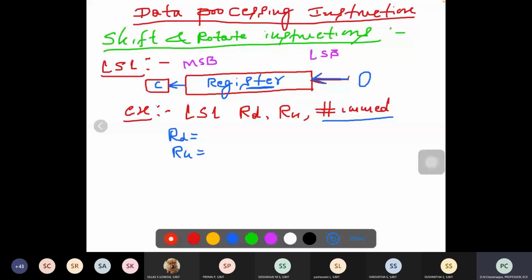When we are using three operands, the first operand is the destination, the second operand is the specified register data. So this is the register data, which data is to be shifted, it has to be specified, and RN is the number of bits to be shifted. It may be shift left or shift right in future instructions, but it has to be specified. Almost similar syntax I will tell you in the next instruction also. And then comments. Comments are very important. You should write the comments.